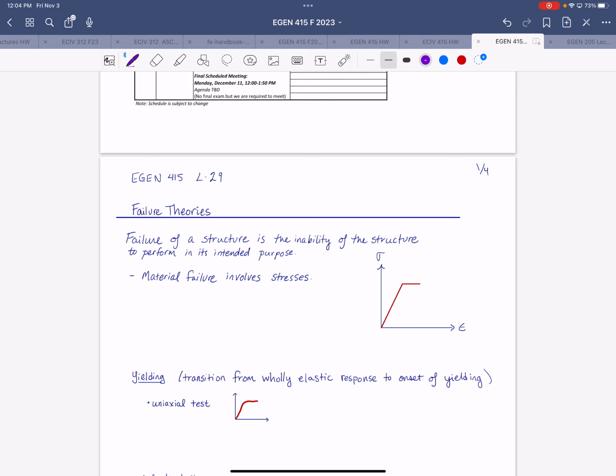But you can intuitively conclude that it's going to be in the second half of the beam's length. So you can put your dummy load somewhere there, set this distance as an unknown value, and then you're basically setting up that integral to solve for the unknown value.